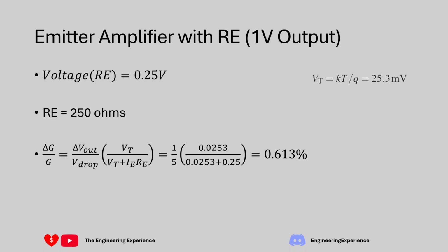If you're following along in the book, there are some graphs that show you the type of distortion that this will cause, so check that out. As the voltage goes up, your gain starts to reduce, so you start to get rounding off. If you have a triangle wave, it starts to turn more rounded as you get closer to VCC, as the gain is reducing.